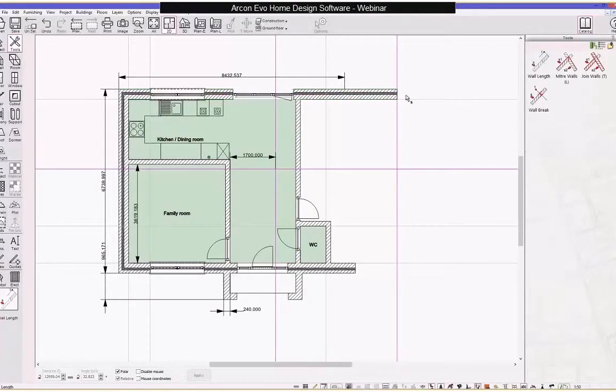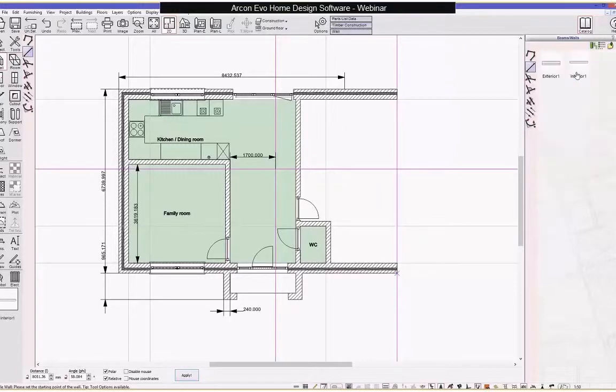I'm going to do the same for this external wall below, and then I'm going to click on the wall options here. I've just created a wall type earlier on. I'm going to click on here and then place this wall in position. As you can see here, I'm using the guidelines to position the wall in place. There are a number of ways of planning out your drawing. You can use guidelines or helplines to peg out where you're going to draw the walls, and that's my preferred method, using guidelines.